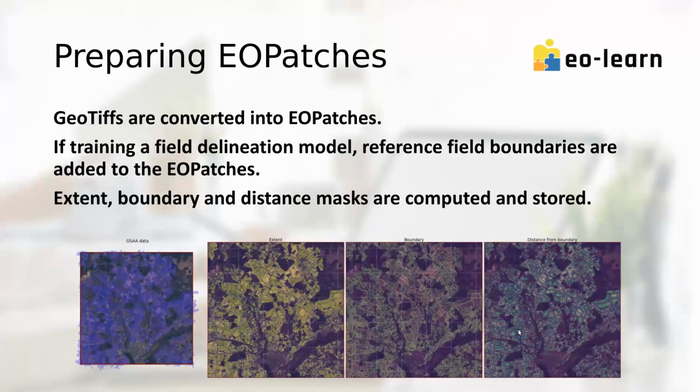But of course, this is another thing that is quite configurable. So the logic here is that if you have some very small boundaries, some very small fields, and you rasterize them and you don't apply a negative buffer, you might show the model boundaries that it cannot see due to the limitation of the resolution. And that's why this part is done.